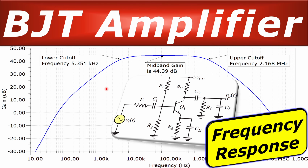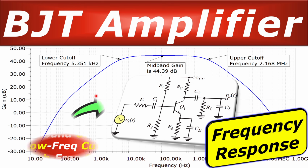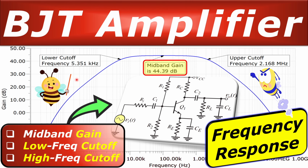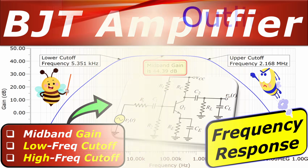In this example we will discuss the frequency response of the common-emitter amplifier. We will discuss in detail three parts, which are the midband voltage gain, the low frequency cutoff and the high frequency cutoff. Of course we will see everything step by step in order to calculate the midband gain, the lower cutoff and the upper cutoff, and we'll also verify these in SPICE simulations.